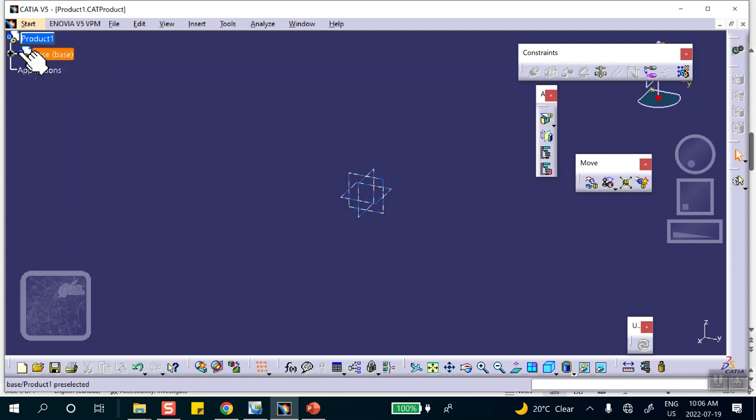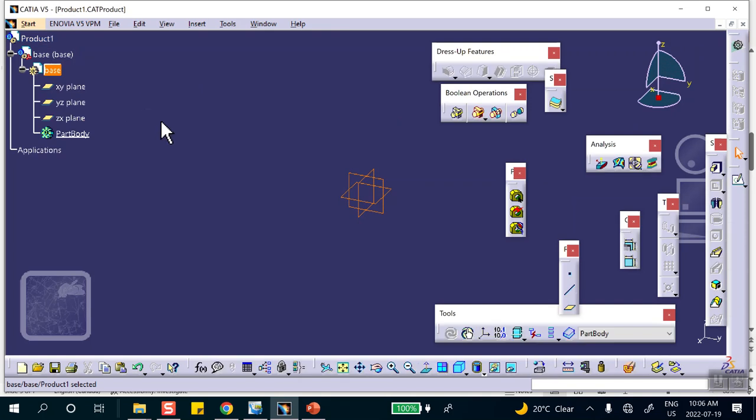because notice that there's 2 gears here. You're in assembly design already. If I double click on this thing, nothing is going to happen. You're already in assembly design. But if you expand this thing, this is part design. That's why you double click on the second line, so that it throws you into the part design. Something that you may not have noticed.